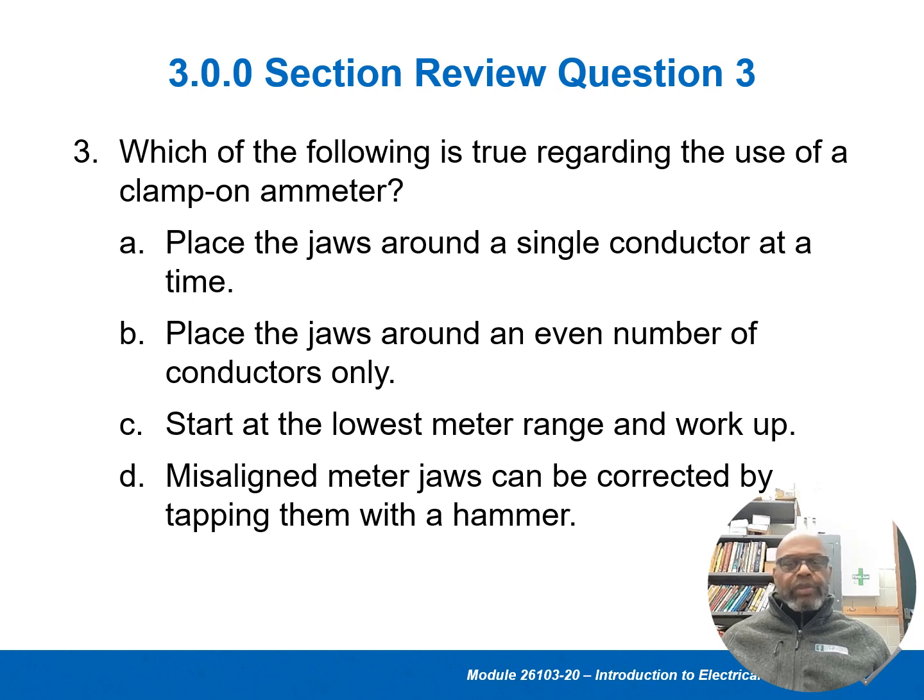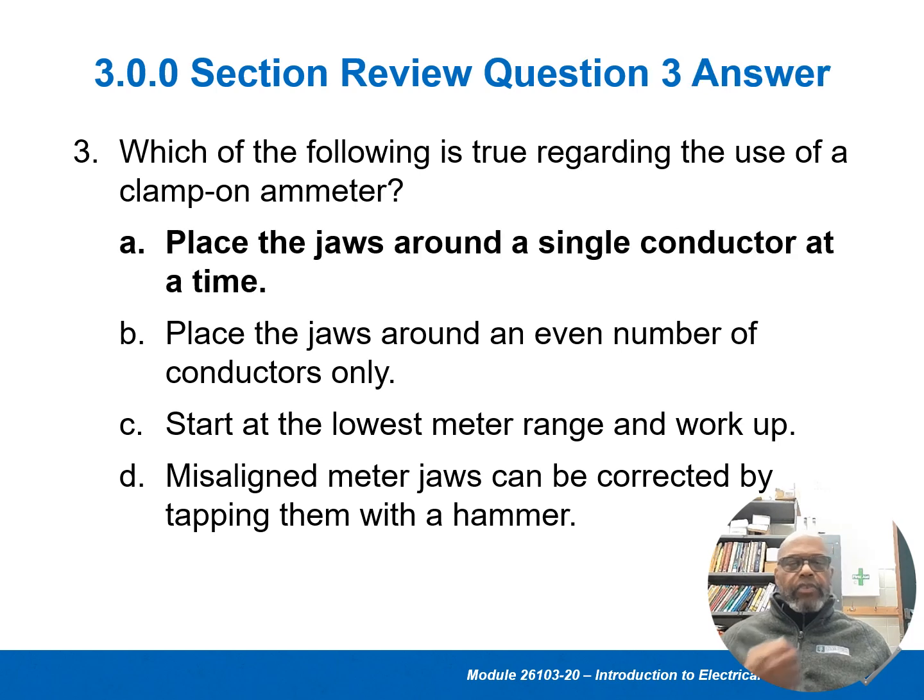Okay, of course, there's only one that is correct. So let's look at this. I gave the answer to it. Let's see if you got it. It is place the jaws around a single conductor at a time. And that is true.